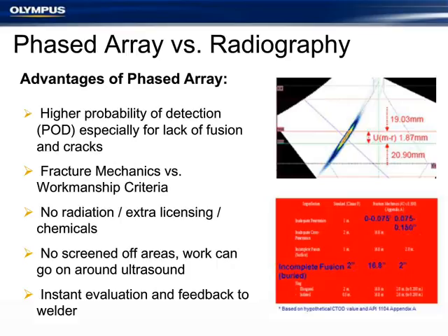As soon as we have the ability to size in the through-wall height or the vertical plane, it really allows us to expand our acceptance criteria, because if we know how the pipe was manufactured down to the engineering level, we might be able to allow much larger defects than what we normally would by just knowing the length and the type of defects. So in the example here, just taken out of API 1104,